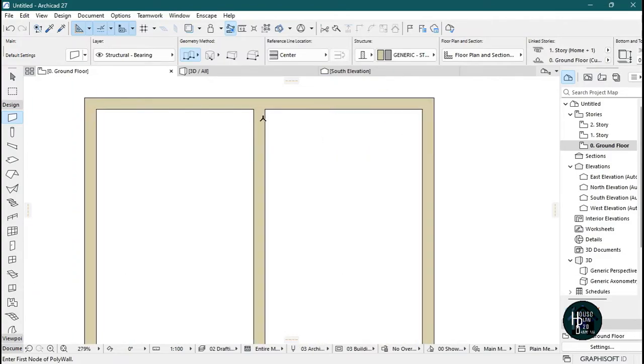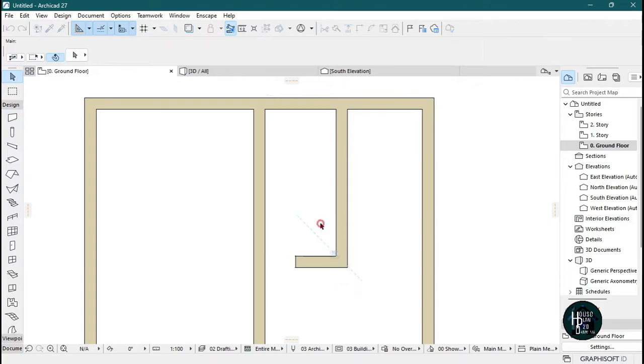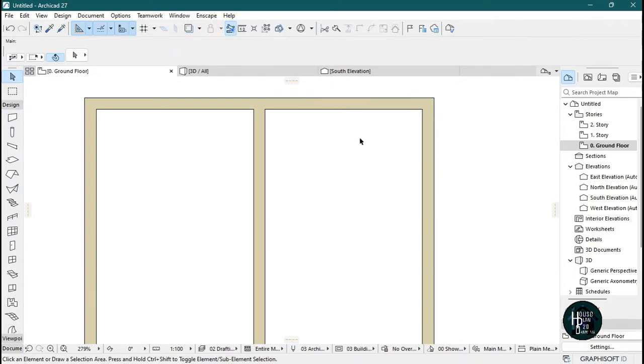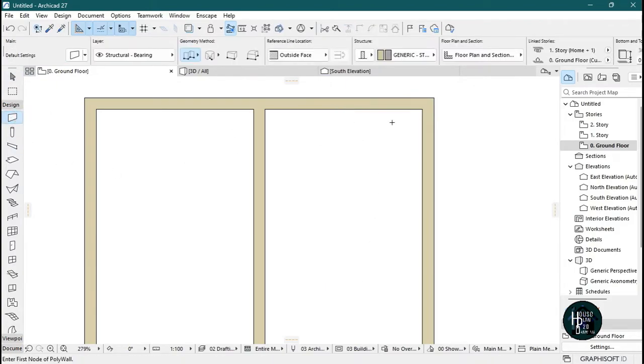Now since we did the center line here, we need a normal line. So if you click this, you're going to be having something like this, so that way you can get the right shape for the building. Okay, so now once you click on the wall, hover your cursor here, allow it to load up and drag it down. Don't click anything, just drag it down, give a distance of 36, then click enter and